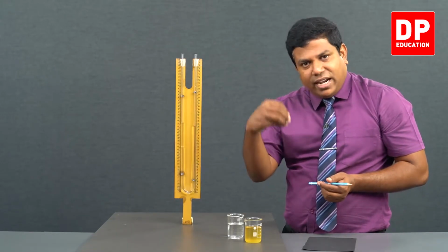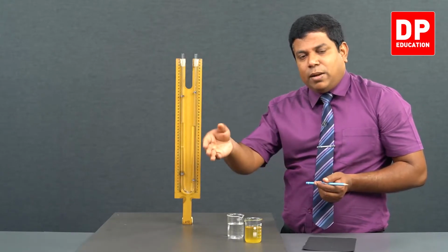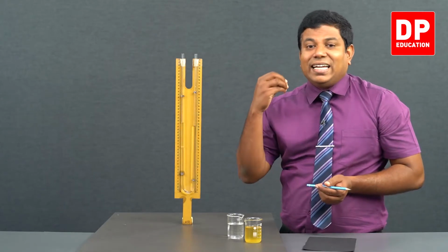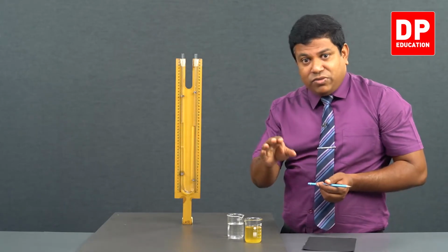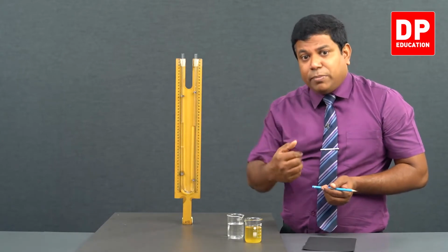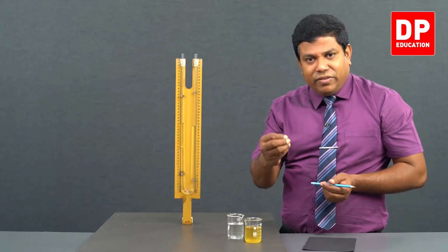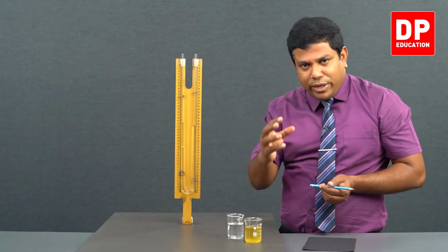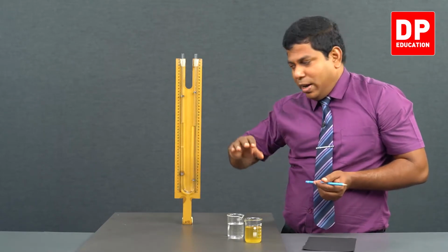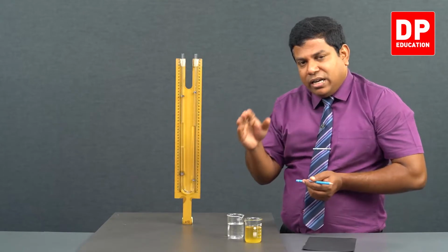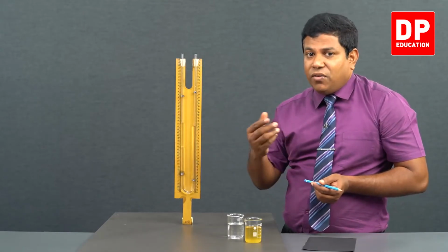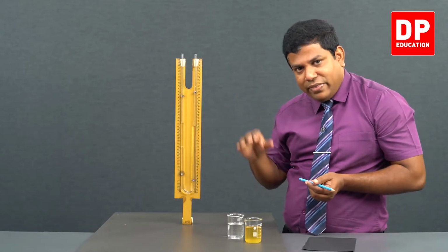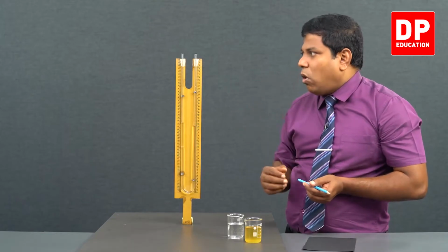Actually, with that itself we can calculate, because HO rho O equals HW rho W. If you substitute these values, you should be able to get rho O by rho W, which is the relative density of oil. Still, since we want to go for a graph, we need multiple readings. For straight line graphs, we prefer at least 4 or 5 readings to get an accurate answer. Right. So I'm not going to stop the experiment with this. I'm going to get another 4 readings. How do I get another 4 readings? I'll add more oil to this little by little, increase the height of the oil column, and then get the readings. So let's add some more oil into this.